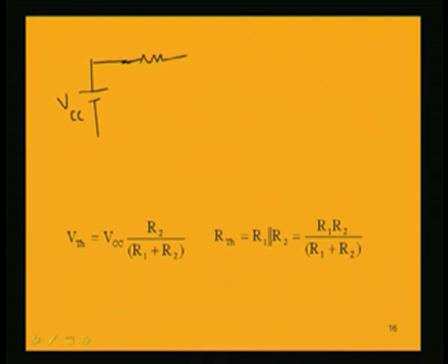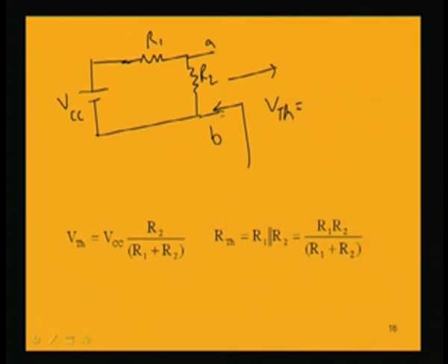Basically, across these 2 points A and B, the right side of this circuit has all those base and collector circuits, but we are finding the Thevenin's equivalent looking from this terminal, that is, across AB. So, the Thevenin's equivalent voltage across these 2 points, V Thevenin, can be found out.